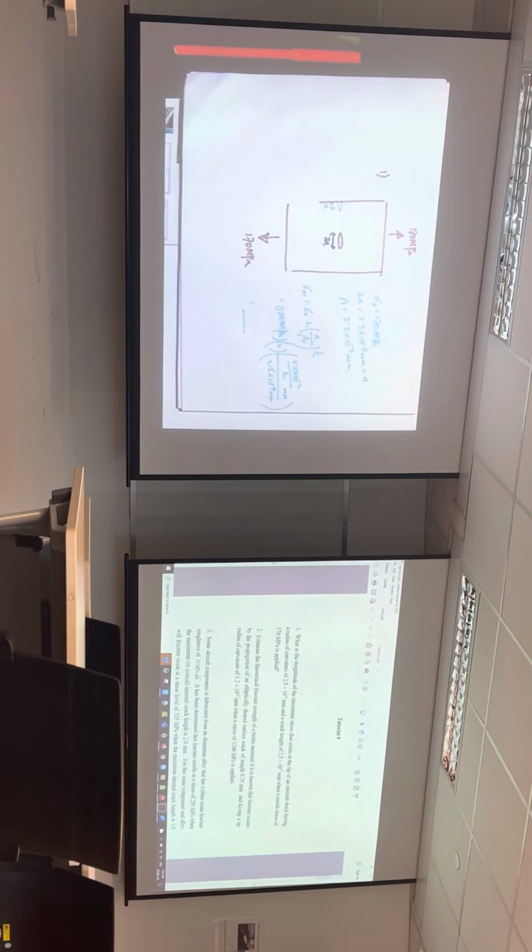But when you're dealing with a ductile material, even if you have a sharp tip, the stress amplification factor can be high, and this can actually exceed the yield strength. What you have is a plastic deformation. The plastic deformation can actually blunt the tip. When you blunt the tip, another way of saying this is that you change the geometry of the tip, the curvature can go down.